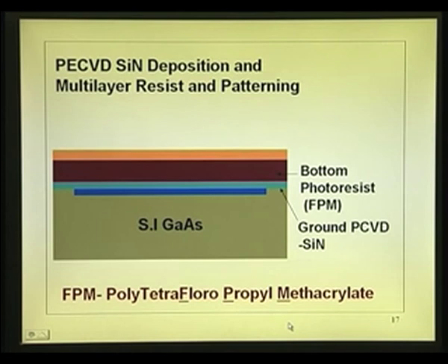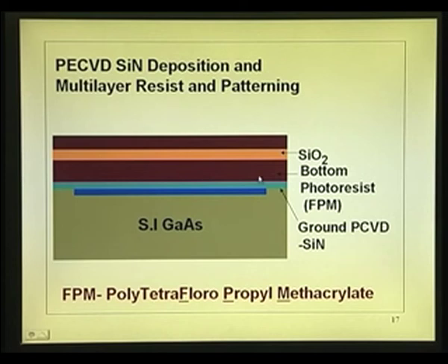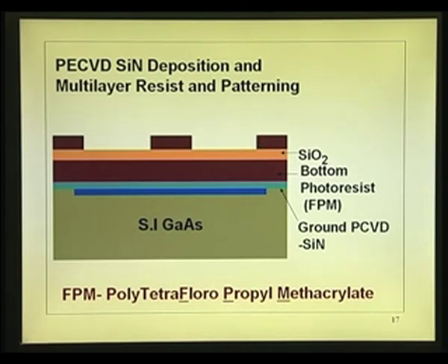Put another layer, which is silicon dioxide. Each one is used as a mask for the next layer, another photoresist layer there. So, you can have bottom photoresist, silicon dioxide, then photoresist, pattern that, open the window there. Now, you can see you are getting an equivalent of that T gate portion now, the center, the top photoresist, okay.